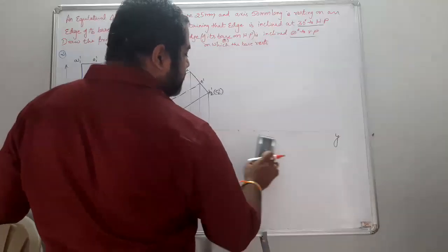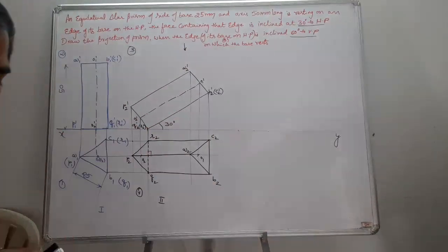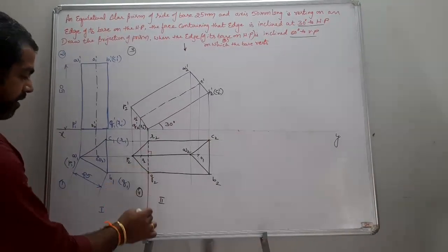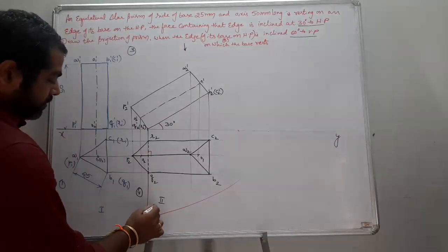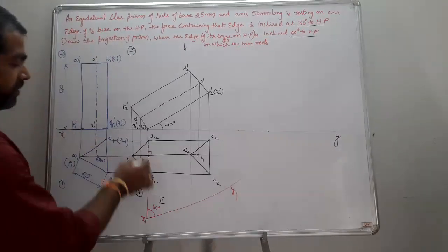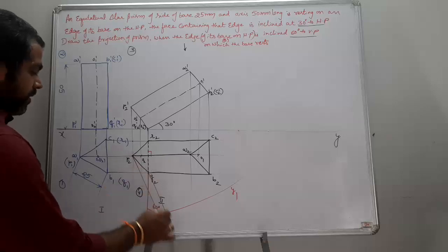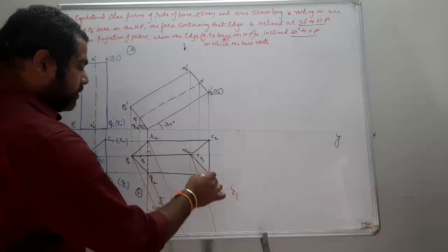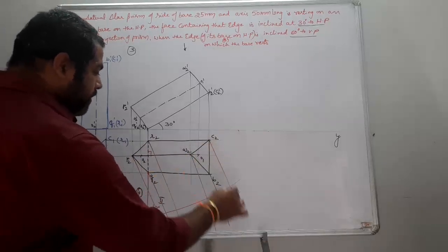so if you have the space that it is permissible, then we can go for change of position method also. If you simply extend this and draw a line of 60 degrees, this becomes your new reference line x1, y1, and you can draw the perpendiculars from all the points and take the distances from the old reference line and place here.